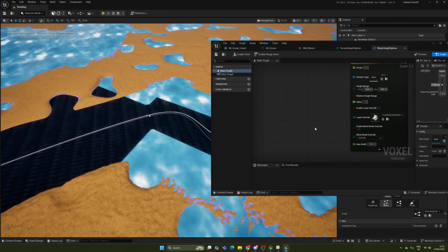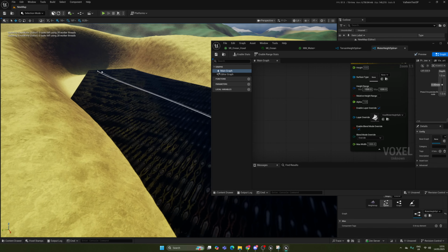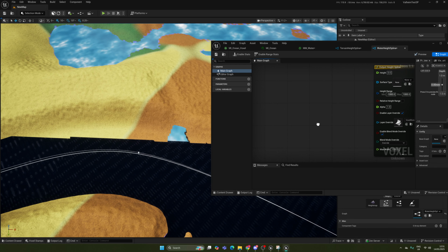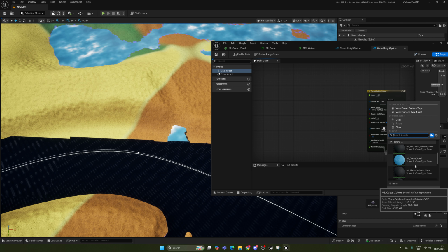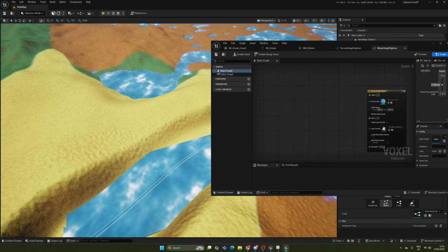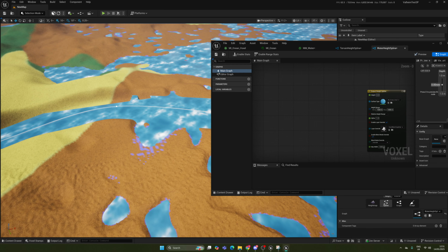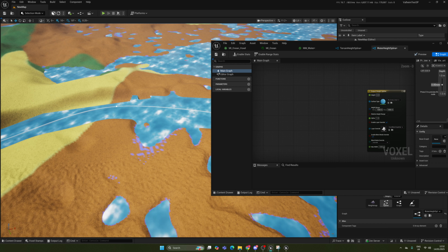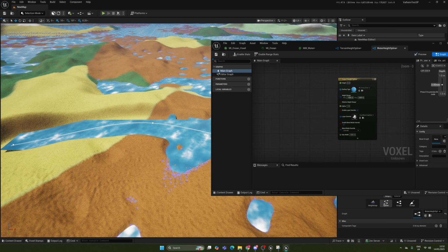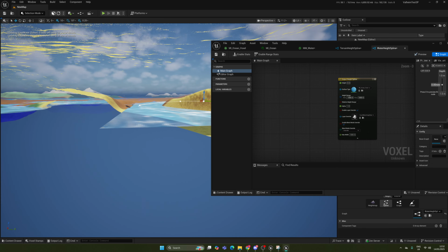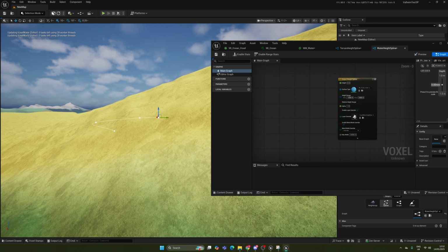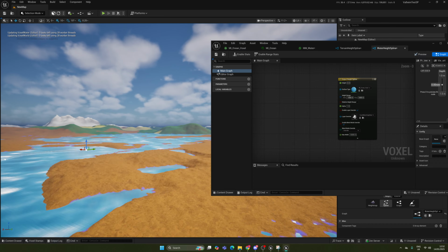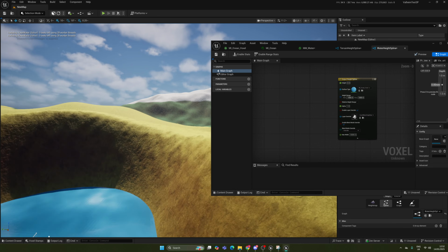So what you can see is, because the height is 0, it's already trying to create a plane at 0 with no surface type. So we can actually just use our voxel material ocean, and it's already started doing something. We're almost there, really. Let me see. What else did I want it to do? I think more or less from here, all we do is just increase the width of it. So if I make this 10,000, you'll see the water plane immediately get wider. Yep. So now wherever this spline is, 10,000 units on either side of it is going to be a water plane, which is not too bad.